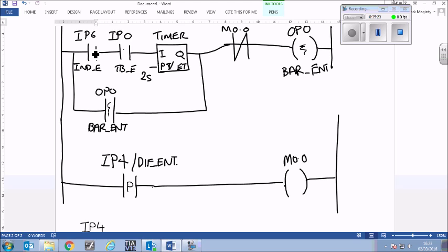Stage 3, the front nose of the car touches the beam of light, not the actual sensor, and then the sensor goes to the off state. So in our chart, that's when it plummeted down. Does this here do anything? The positive edge, does it? No. It only detects when it goes from off to on.